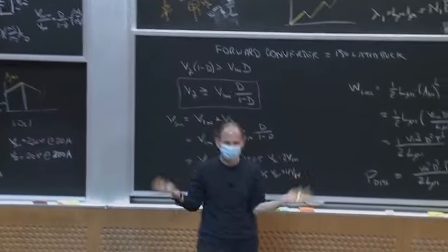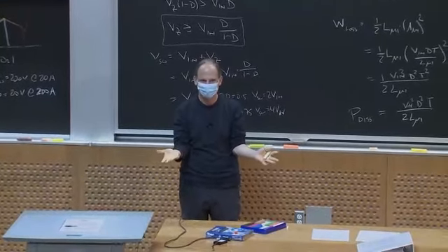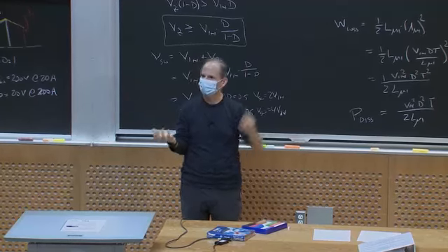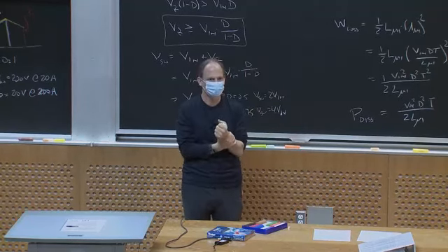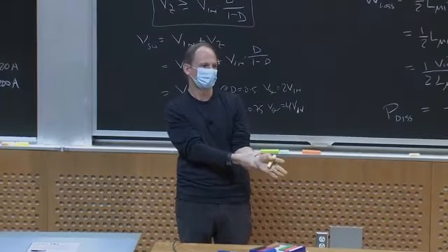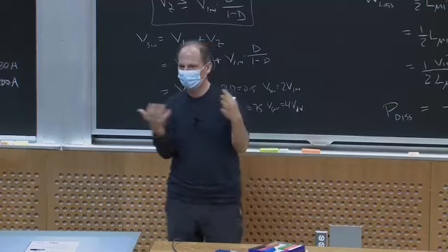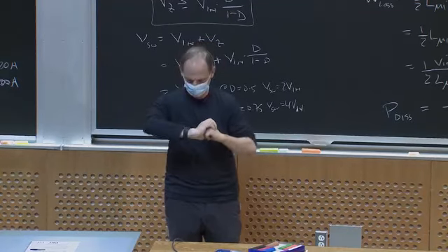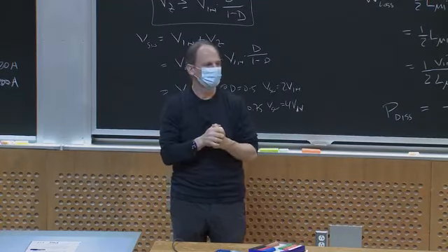Okay, so there's lots of ways to recover that energy. And the trade-offs of how you do that separates different versions of the forward converter from one another. So I don't want you to walk away with the notion that I have to throw away the energy stored in the transformer. I don't. I can recover it. But it adds complexity and adds some trade-offs. Okay? Any final questions?